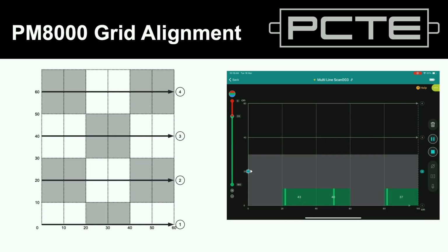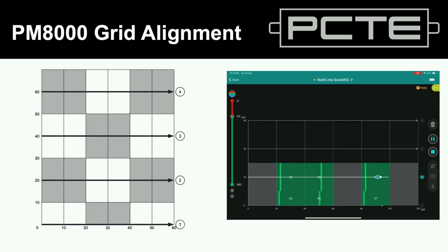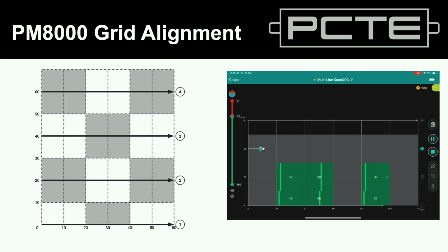If I know the depth of the closest bar to the surface in a region of my structure, and I do half cells in the same region, and I keep my grids identical between the two, I now know whether they're likely corroding and how close they are to the surface. And maybe if I've got some chemical analysis, I can start to form relationships and do some thinking on the corrosion and durability side that is enabled by this visualization.